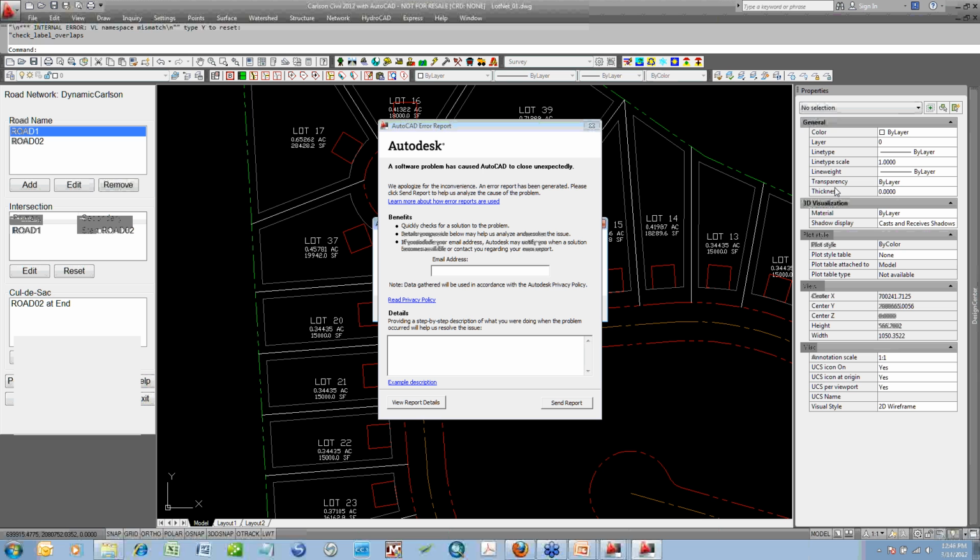And for this one, I believe that you absolutely must have a profile for the main run. But for each lateral, if you're adding full catch basins on the end of that, I believe you can do that without having to have a profile for each one. However, it will be drawn on the main run profile.